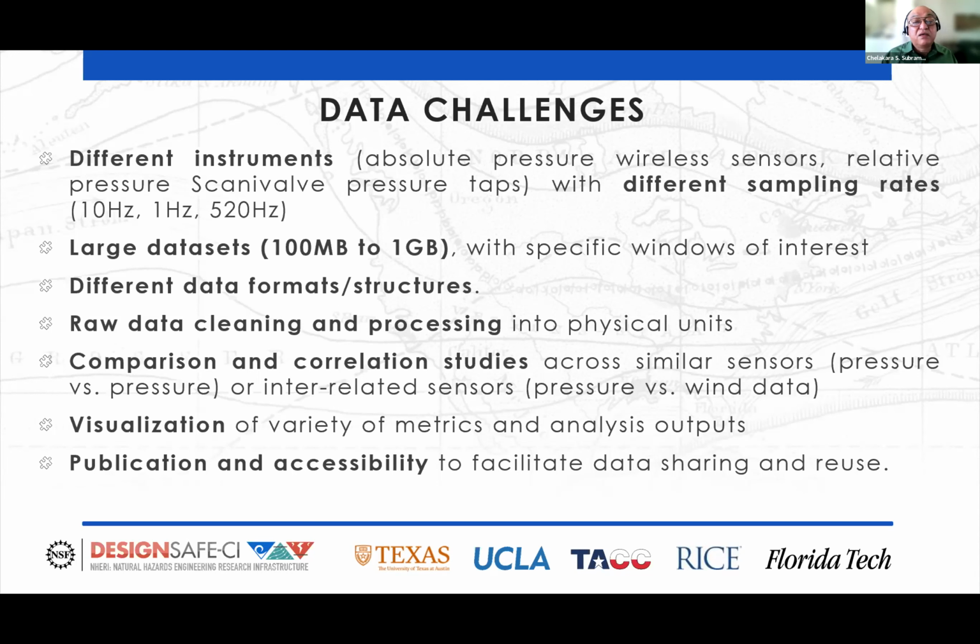Then, of course, in the field measurement, particularly in the wireless measurement, you are likely to have some noise because, even if our system is noise-free, we also share the communication link, Wi-Fi links and all that, which cannot be guaranteed to be noise-free. So there will be some contamination due to communication problems. We may have extraneous noise. So we have to clean up the data always.